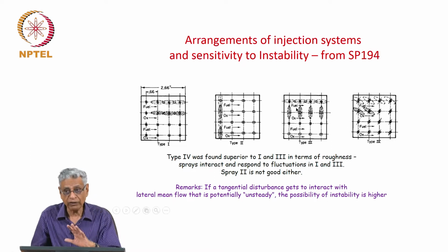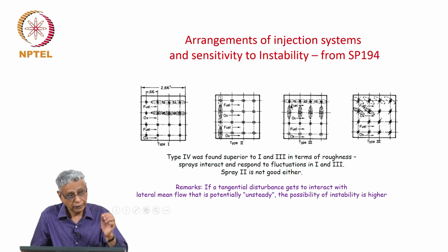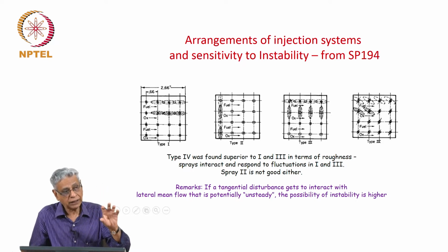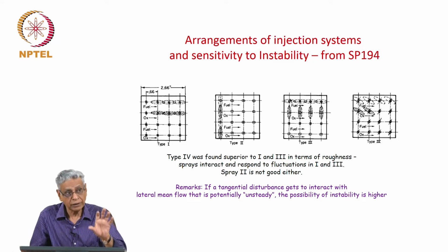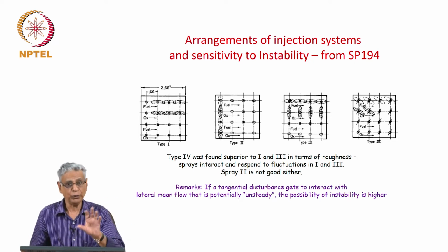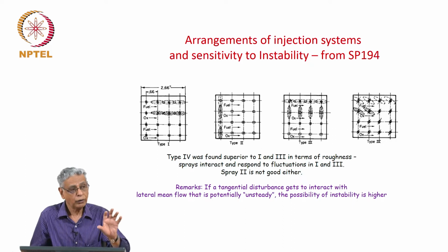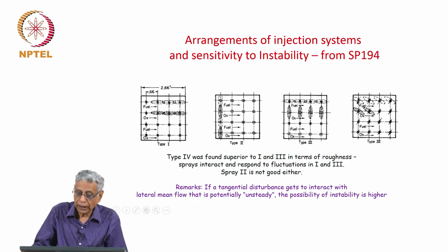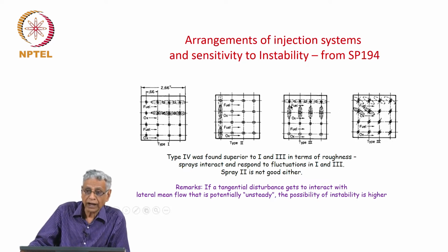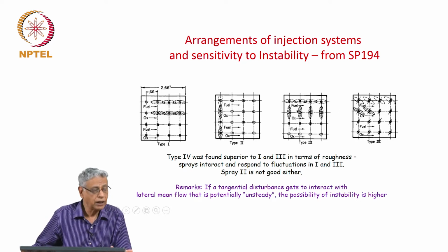There is a heat release profile here, and because of the vaporization and combustion locally, the interaction which is taking place between this heat release distribution and the acoustic oscillations disrupts even the mean energy distribution, and it happens in phase, and that's why you have the instability. So that is why they claim that when the degree of interaction is much more, instability is higher than where the degree of interaction is lower.